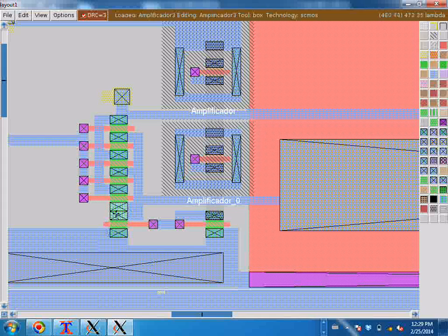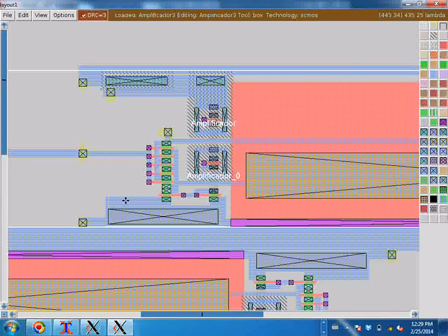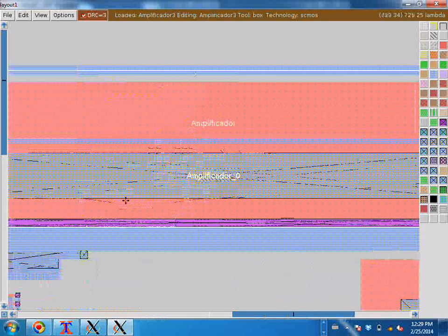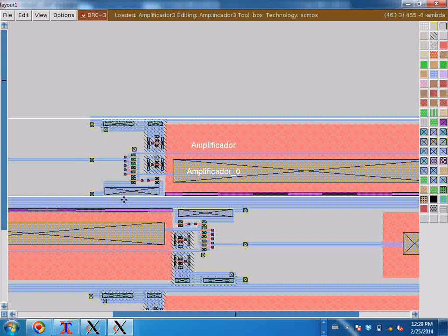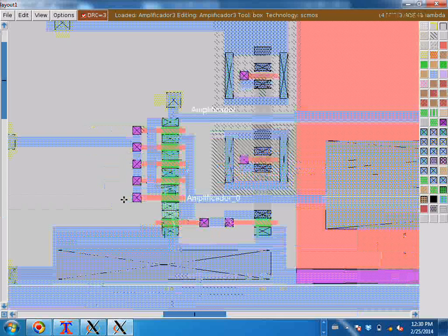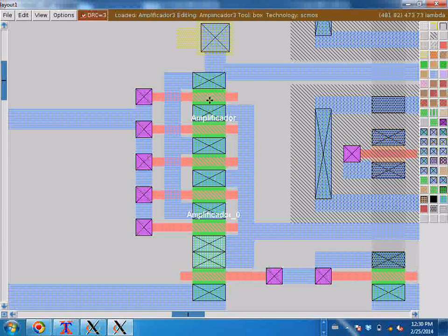Here's a design rule violation, but I don't care about this because it's because we are using hierarchy, but we can prevent that from happening. Here's a capacitor, a big capacitor, and actually that's the way you design a chip. This is it. It's no more complicated than this. Yeah, it looks like PCB, but each transistor is something you draw by hand. That's how it works. But it's not that complicated.